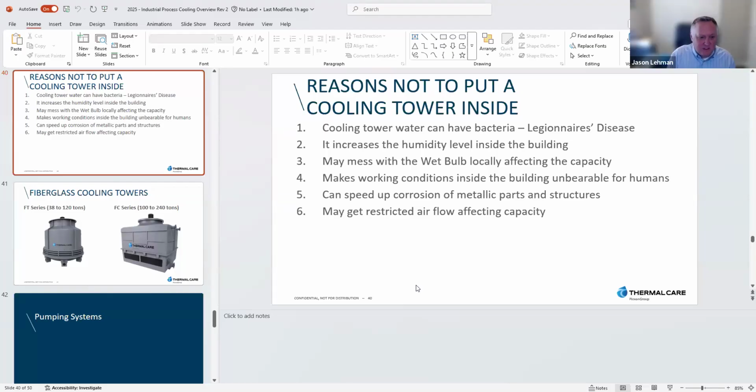Yeah, another question here, buffer tanks, is there a minimum loop volume? And do you require buffer tanks? Yes, we do. Buffer tanks for process, it's good practice to be somewhere in the 6 to 10 gallons per ton range. And the reason for that is the chillers have hot gas and they will react.